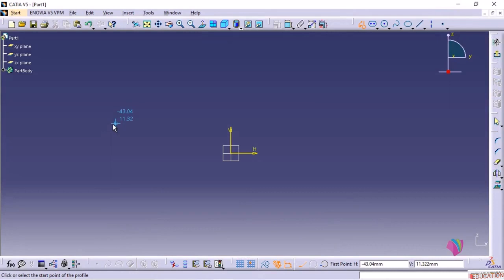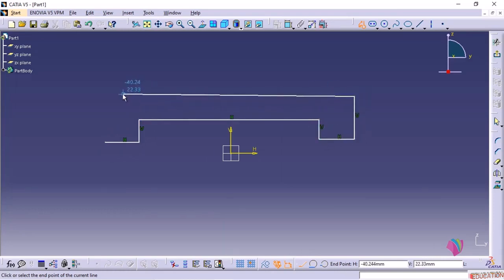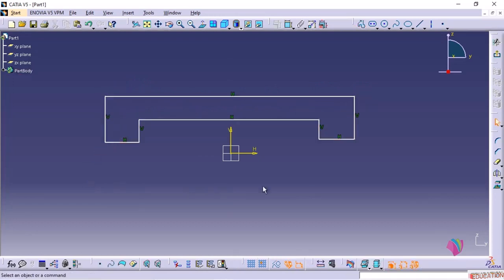If you have a drawing which is symmetric about the center axis, then you should always create the sketch symmetric about this datum axis. So let us create the drawing symmetric about this vertical axis. We will create a rough sketch. I'll select here to create the first point, second, and you can see I'm creating a rough sketch. It is just a rough sketch, so you can create as you like. First, let me position this. I'll select this line and this axis.